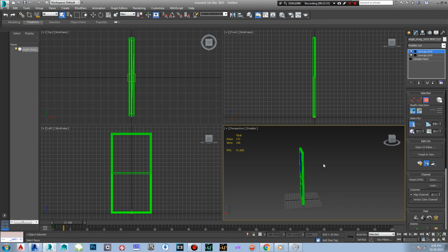You can change that, but you also have to change it across all your programs. You just have to think ahead. You know what I mean? If you do feet in Revit, how many centimeters are in a foot? Well, 3ds Max is going to put that many centimeters to fill up. Let's say I put 8 or 9 feet for the wall height. How many centimeters is going to be in that? A little over 6 feet is 183 centimeters. There you go. Just do the math.